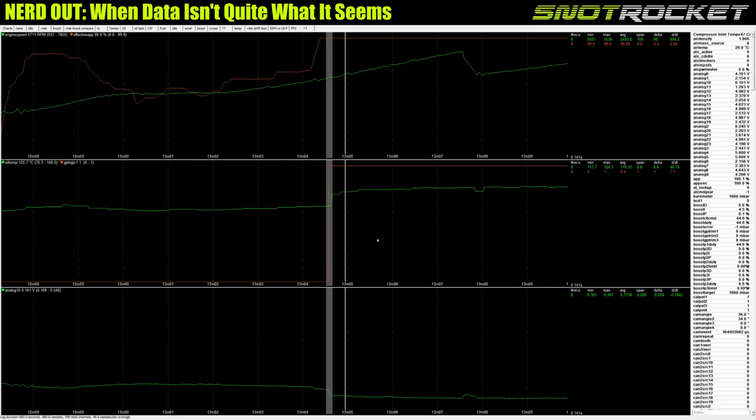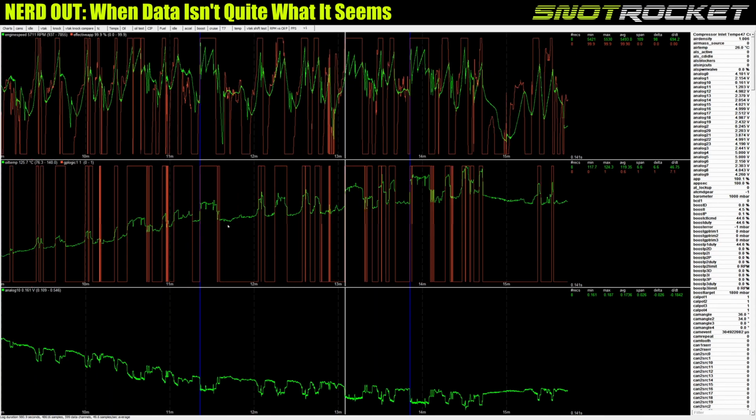The data that we're looking at here, the oil temperature data, was obviously wrong. Oil doesn't shift like that. Anybody that's an experienced calibration engineer or a log analyzer in a race team, or in automotive engine development, would instantly look at that and say, well, that's not right. Oil doesn't do that. That's a noisy signal. But going back and tracing it through, using the data to prove that the data is wrong,